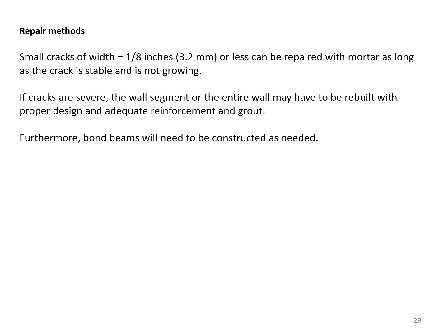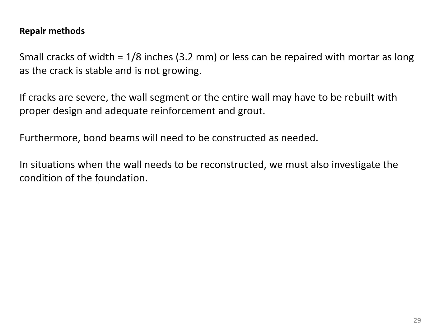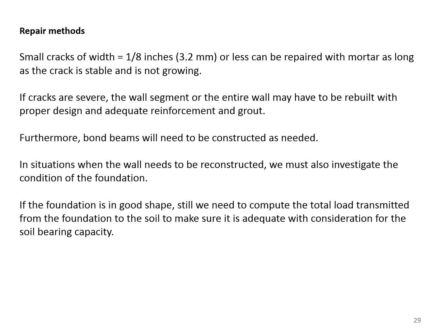Bound beams may also need to be constructed as needed. In situations when the wall needs to be reconstructed, we must also investigate the condition of the foundation. If the foundation is in good shape, still we need to compute the total load transmitted from the foundation to the soil to make sure it is adequate with consideration for the soil bearing capacity.